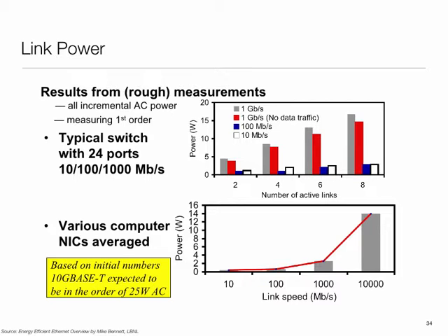This is the same slide that I had earlier on. If I look at a network interface card and its power consumption, this is the Ethernet chip and the PHY chip, which sits in front of the Ethernet and drives the signal on the cable, both on the computer side and the analogous part on the port side. What you see here is a gigabit per second link with no data, a 100 megabit link and a 10 megabit link. And as you would imagine, this is the power consumption as the link speed goes up. Yes, you pay for higher performance quite dramatically.